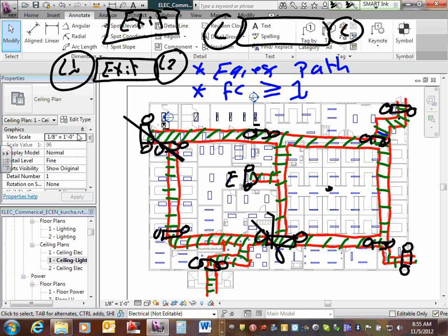Can I have thumbs up, Chad? Now, if you're doing your business in the bathroom here, what do you think, and you lose the power? So now these are the egress path. Now there's also another good application for certain areas to have an emergency light. One example: I have bathrooms, so I would like to drop one here for the bathroom. If people are doing their business, this is a light only. How am I going to specify light only? I'm just going to put E in front of the light only.